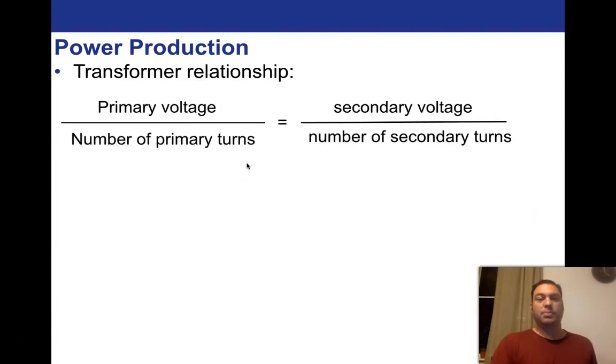And so the proportionality is pretty straightforward. You take the primary voltage, say 10,000, and there's some number of primary turns associated with that in the transformer. If we want to get the secondary voltage to 110, so let's keep it simple, let's go from 10,000 to 100. That means that the voltage here is 100 times larger. To be able to get that, the number of secondary turns needs to be 100 times smaller than it is over here. It's just a proportionality argument, right?